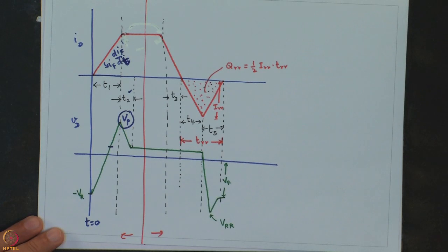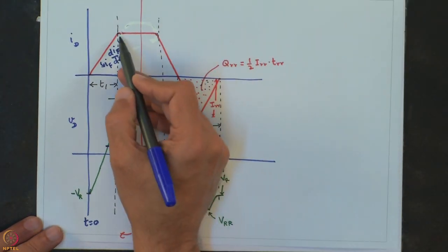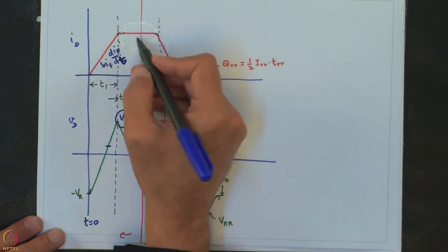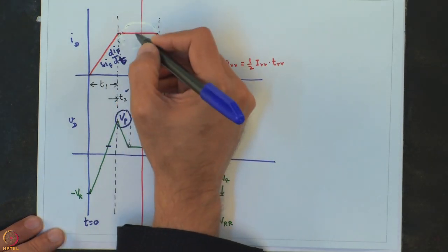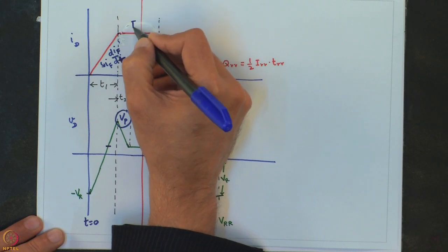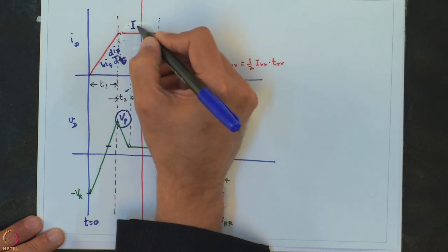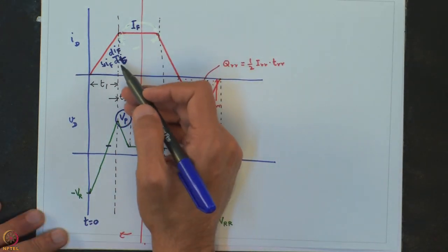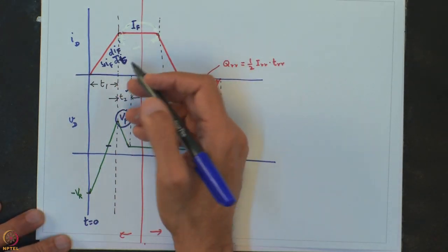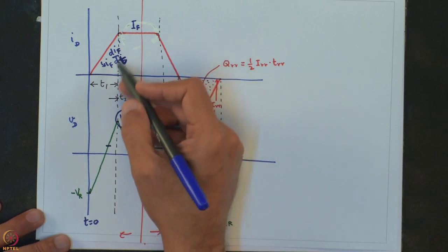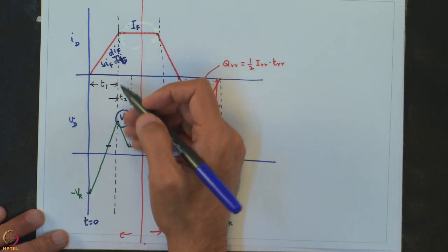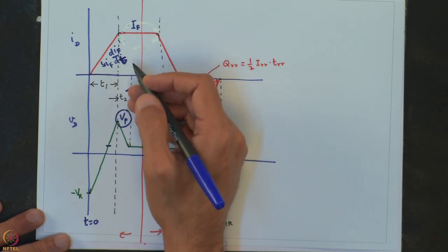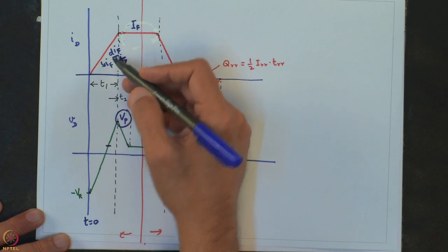Now what happens during T2 is that the diode current has settled to a constant value here. So let us say this is the constant value IF. The excess carriers have now all built up. So the losses or the voltage drops across the N minus layer have also reduced drastically. And because of the conductivity modulation that we have seen before, you have very low drops there.